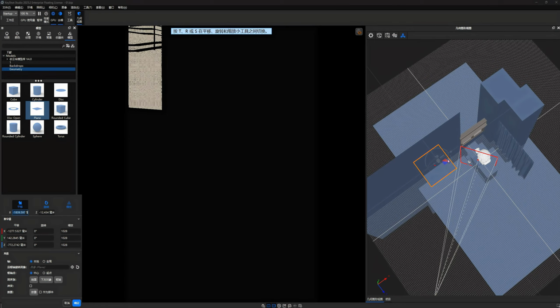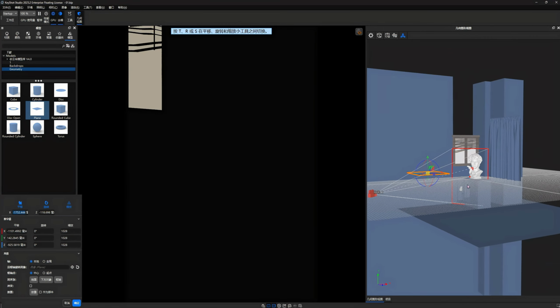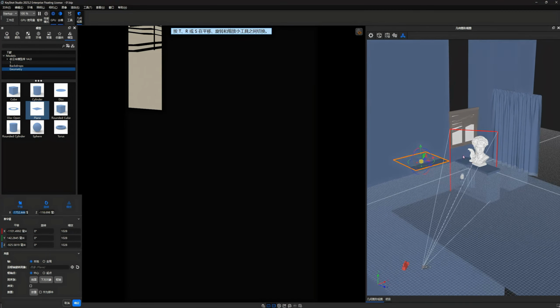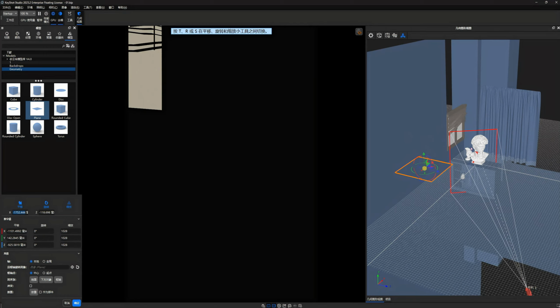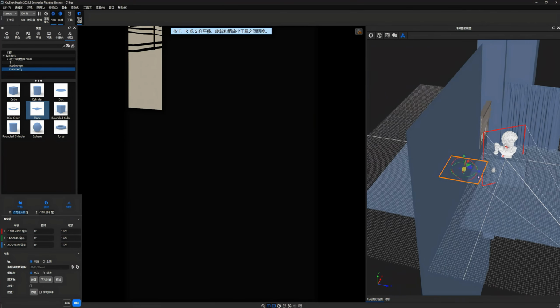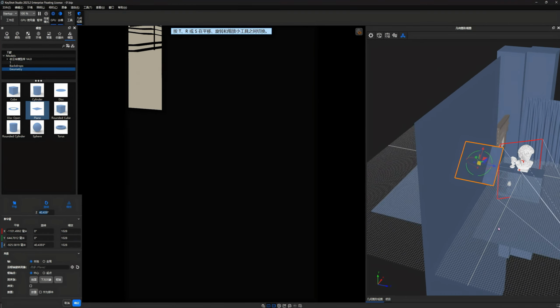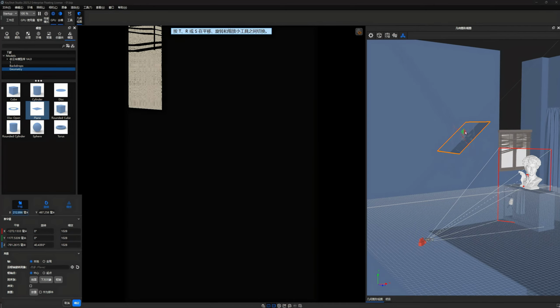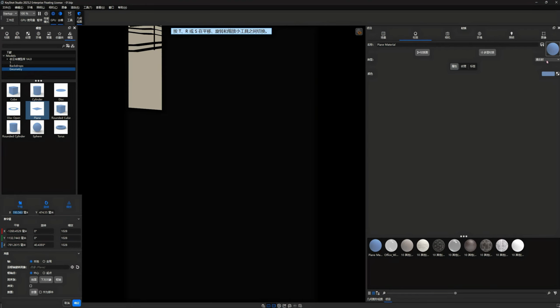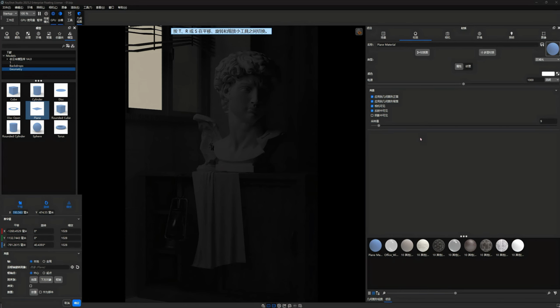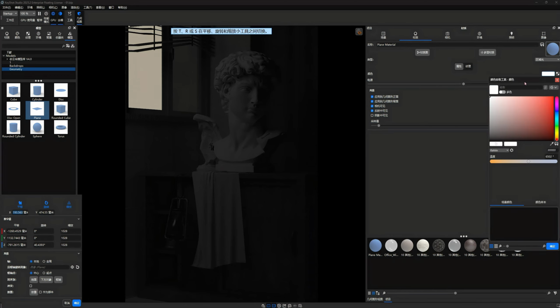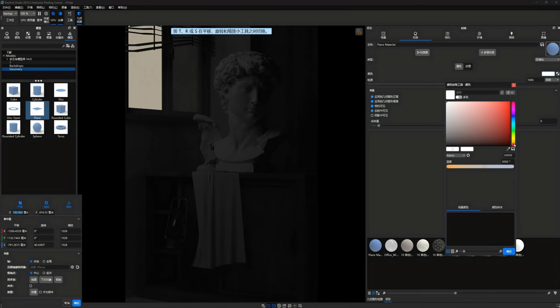Just move it. I want this light taken from this direction towards the plaster. So what's my first step? Adjust its position first. Okay, double-click it. Turn it into a material for an area light. Okay, now it works. First, change its color. Make it yellowish.